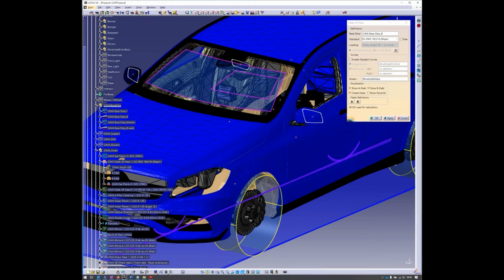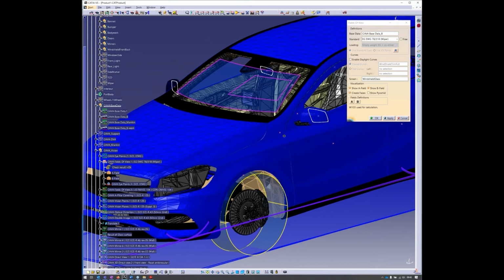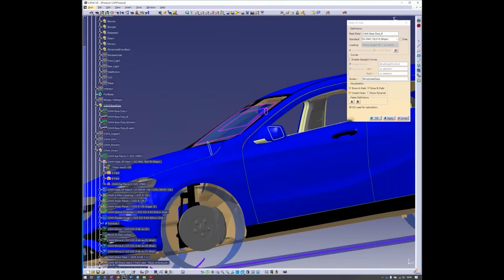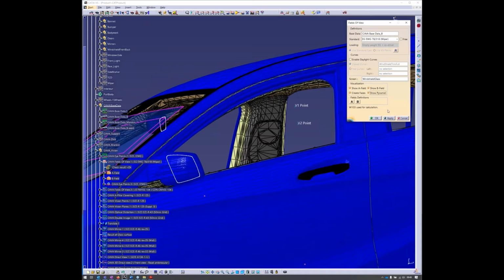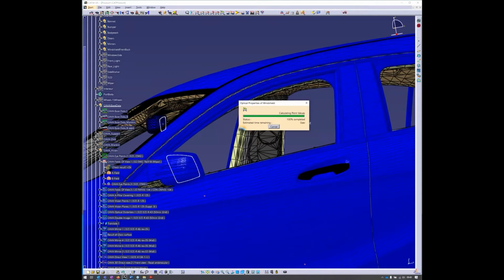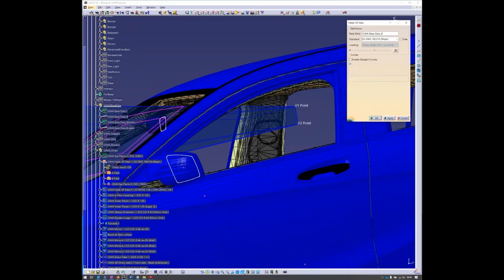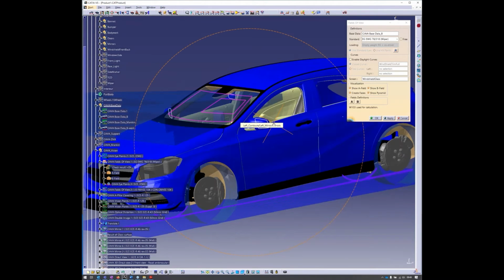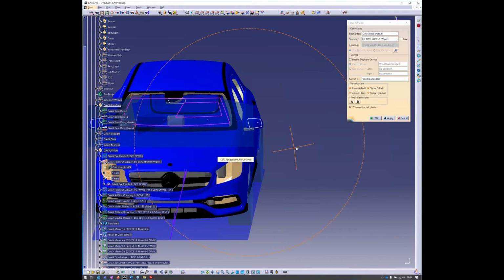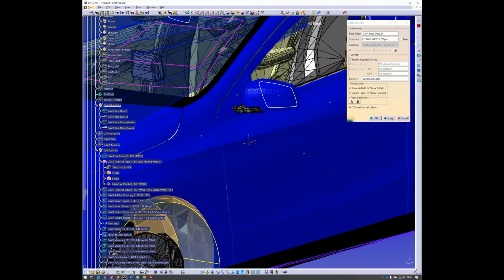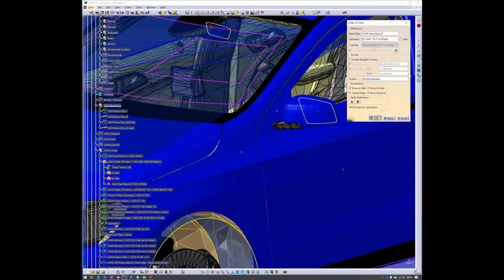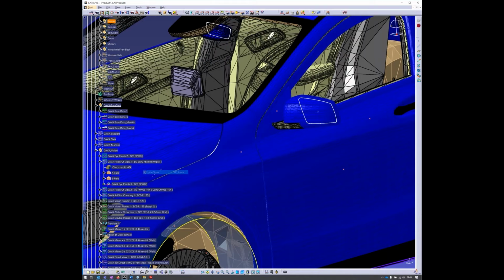CAVA helps you here to create these fields of view very easily. The only input required is the seating reference point in the base data. This will then automatically create the required eye points, in this case, the so-called V points, from which you can determine the angled planes that make up the fields on the windshield. So you can also show these angled planes. And you can see how these fields are defined with the help of these pyramids, and you can see the resulting output very easily. This is available for the European standards, but also for the American standards.